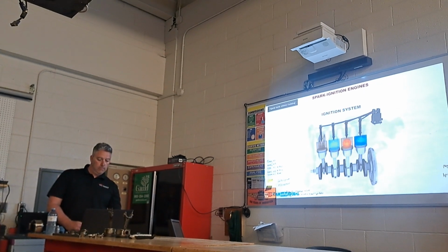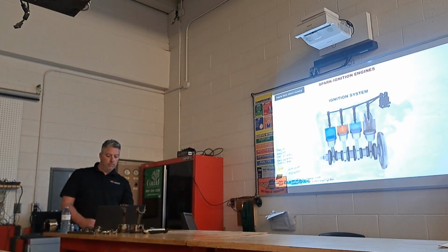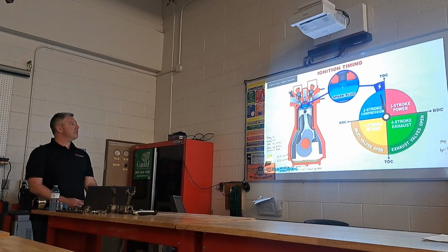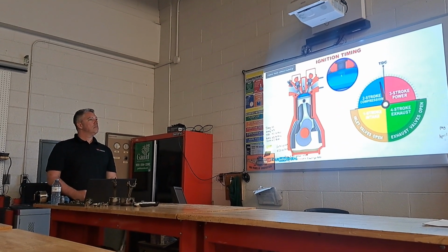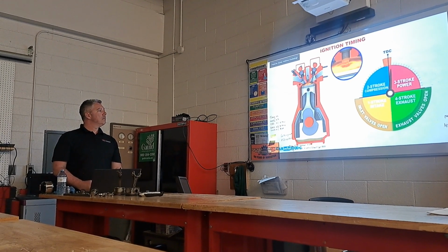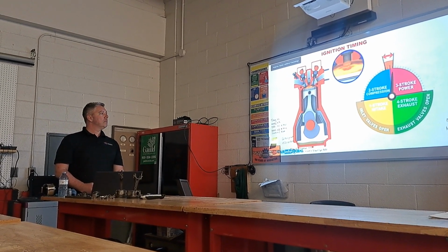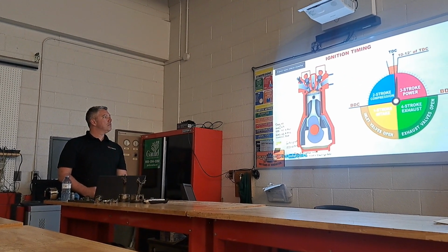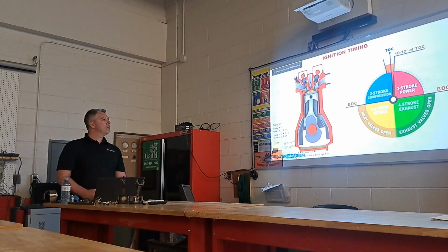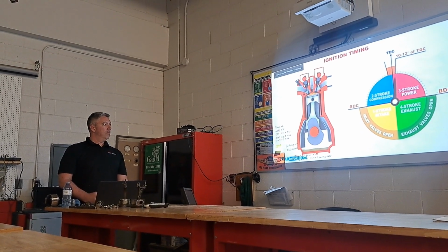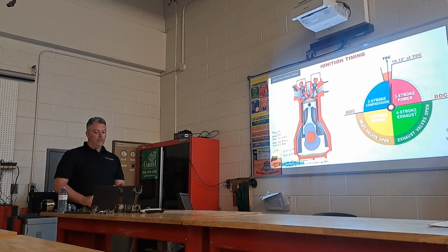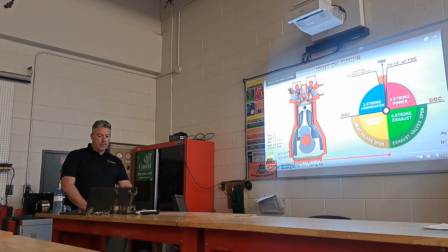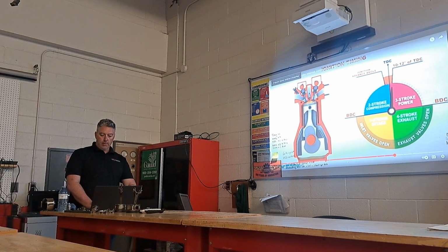Ignition timing is critical to the efficient operation of the engine. There is some time between the appearance of a spark and the complete ignition of the fuel-air mixture and the maximum gas pressure. The piston moves some distance during this time. For maximum engine efficiency, the piston must be within 10 to 12 degrees of top dead center at maximum gas pressure. It means that the ignition system must start in advance. The moment at which the spark plug fires is called ignition timing. We'll continue that later on next week.